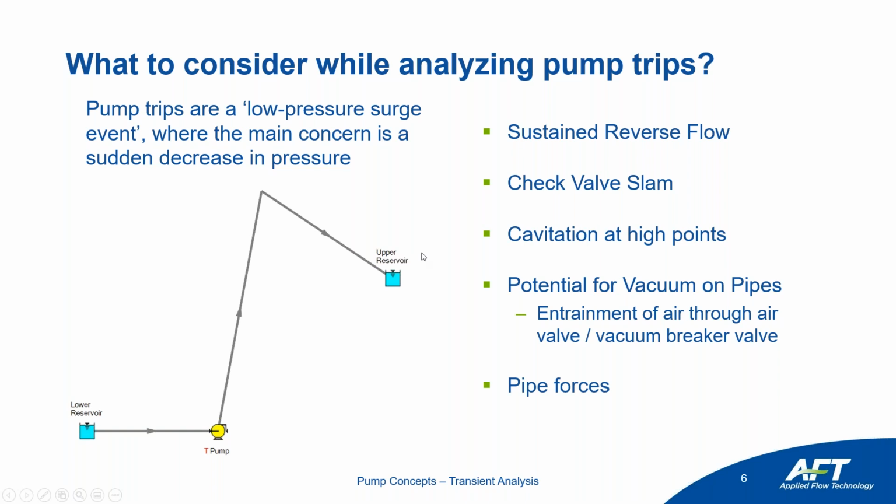Finally, again, pipe forces. So anytime that there are pressure swings, anytime you're doing transient analysis, you can also address pipe forces. And this largely depends on the magnitude of the pressure change as well as how quickly it moves through the system. So let's take a look at doing a pump trip in the software.